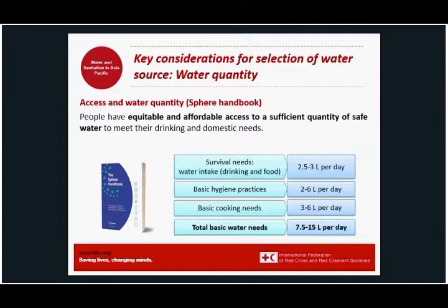These poor sanitary practices lead to poor hygiene, which combine to increase the risk of water-related disease. According to Sphere Water Supply Standard number 1, we need at least 7.5 liters per person for the first phase of a disaster. Then, moving on, 15 liters per person at the earliest possible time. When we talk about quantities of water needed for domestic use, it is very much context specific. It may vary according to climate, available sanitation facilities, people's habits, religious and cultural practices, food that they cook and eat, etc. Therefore, 15 liters per person per day can be exceeded to conform to local standard where that standard is higher.